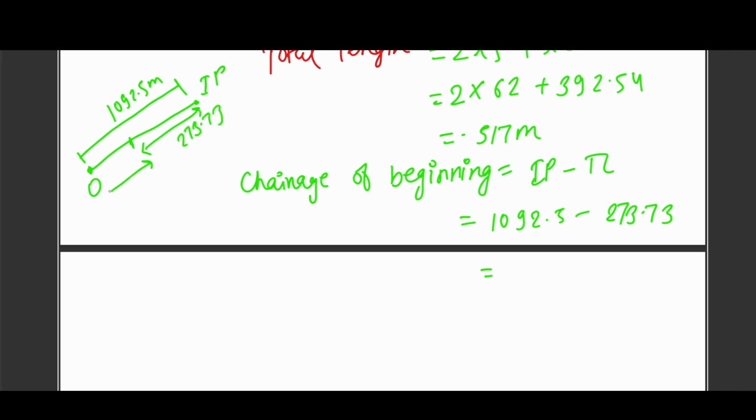So we need to find this distance, so we subtract this from here. If the chainage is given as 1 plus 000 meter, then it means 1000 meter. If it is like 2 plus 725, then it is 2725 meter. Like this the chainage will be. If you are confused about the chainages, then the question is okay like that.